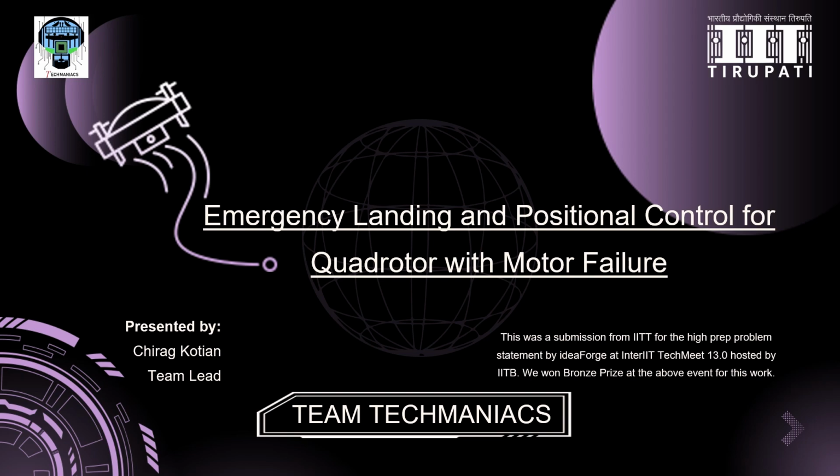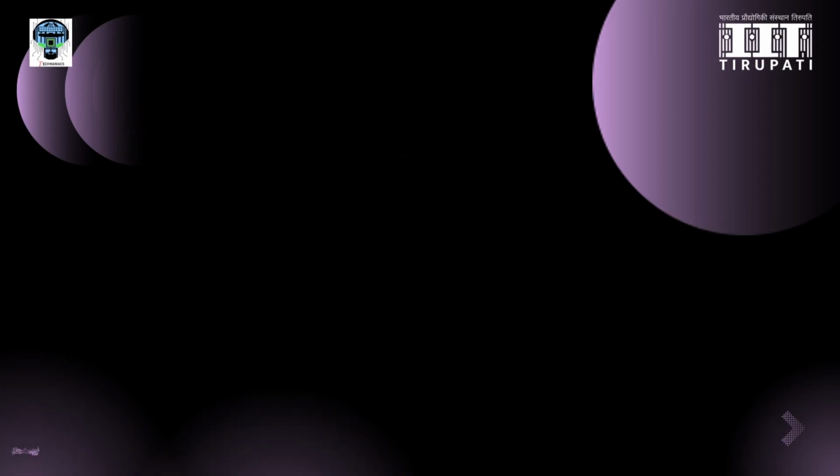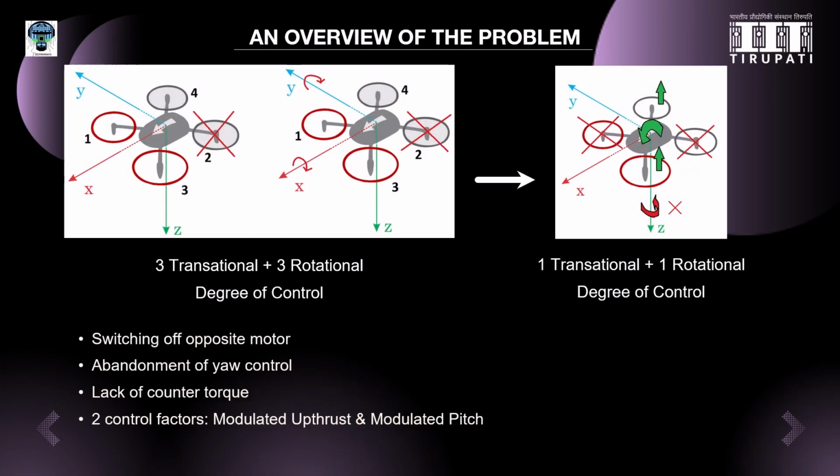In this project, we tackle that problem head on by deciding to abandon yaw control and focus on what can be controlled. Our key insight is to let the drone yaw freely instead of fighting the spin. Yaw, rotation around the vertical axis, becomes uncontrolled after a motor failure, but the drone can still use thrust and tilt to descend safely. In effect, we relax the yaw constraint.